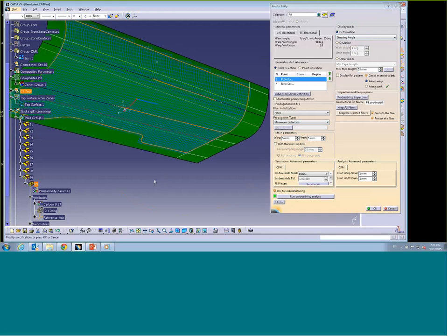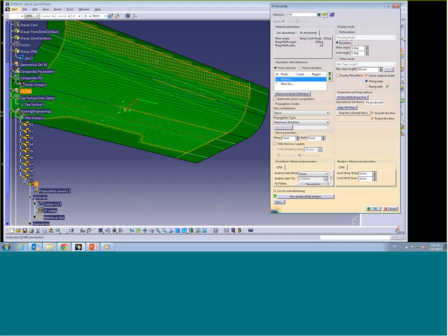And the deformation is the shearing angle. Essentially, when I drape my fabric over the mold, the formerly rectangular cell will become skewed a little, so it tells me by how much. And the blue color means it's under the warning angle of 5 degrees. And you know, this one, it's a pretty simple model, so it's pretty good. And the second one, I can also check deviation. So deviation tells me by how much the orientation of my fibers deviates from theoretical orientation.